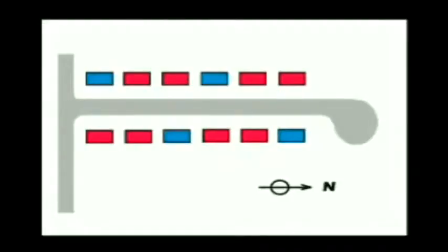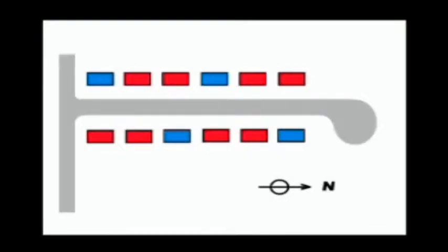Looking at this site plan, you can readily see how the experiment was set up. The 4 houses are the control group. The control homes are wall-vented crawl spaces with the foundation vents left open all the time. And be sure to notice how 100% of the earth floor in these crawl spaces is fully covered with a ground vapor retarder of 6 mil polyethylene. Coming back to the site plan, the remaining 8 houses are the experiment group.